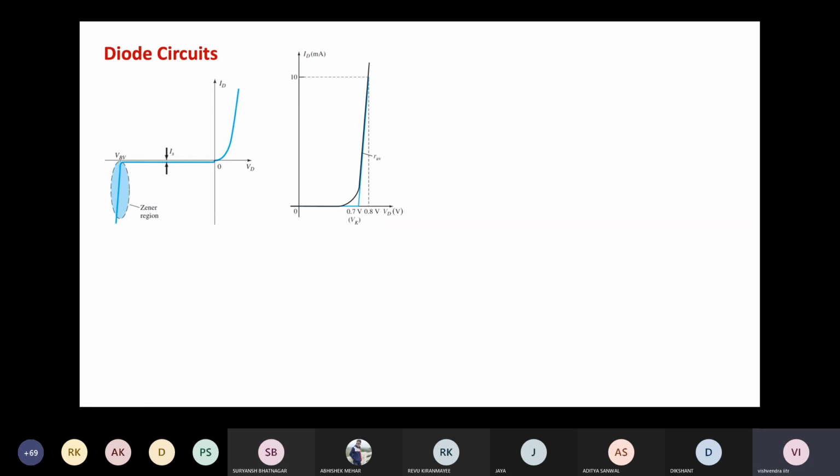Okay. And in the forward bias in circuits, generally, and this is also clear from the characteristics of the diode, for up to, let's say, in the case of silicon diode, up to 0.7 volts of forward bias, the current is extremely small in the diode, and the current abruptly increases beyond this voltage, and that's why we see this kind of exponential trend in the characteristics.